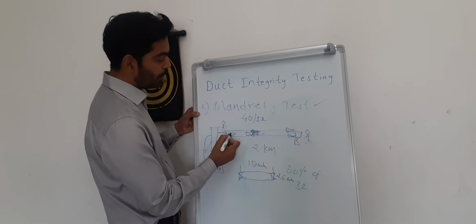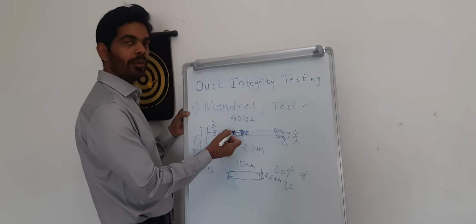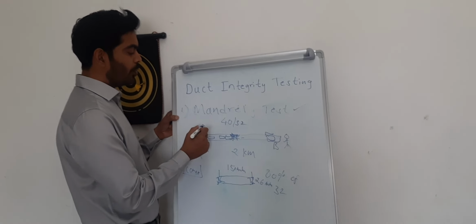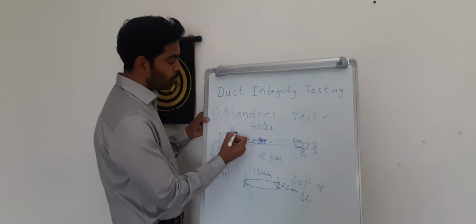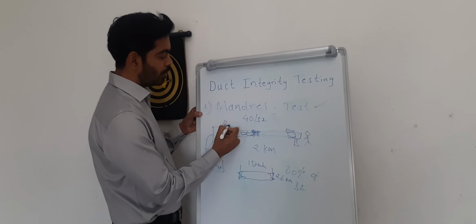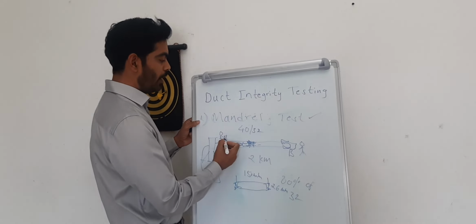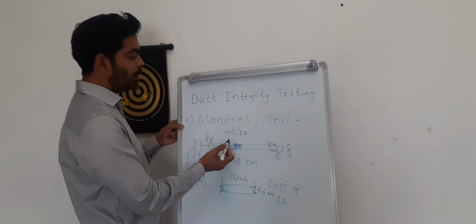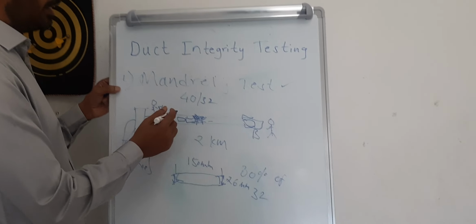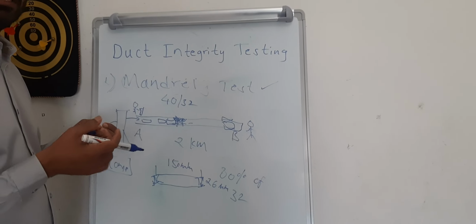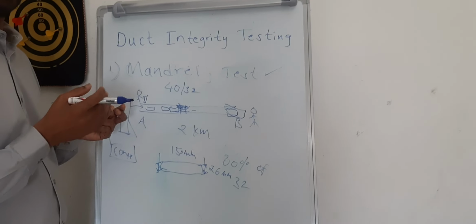What will happen is, suppose this is your transmitter, it will go and get stuck behind your shuttle. Then you have to again turn off the compressor. One person has to walk with a receiver, a device somewhat like this. This person is holding it in his hands, and he is walking along the path. Once he approaches where the transmitter has stopped, exactly there the receiver will start getting signals, and it will make sounds also, and you can pinpoint this location where it has got stuck.